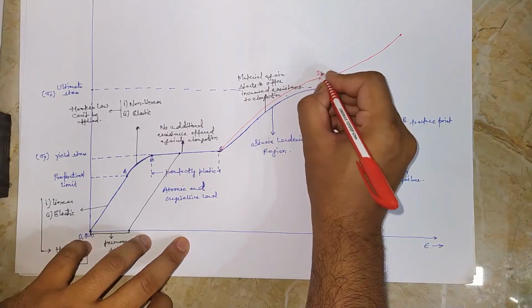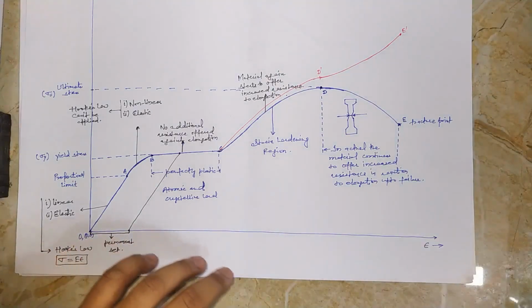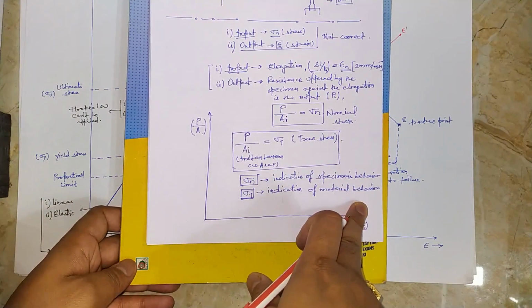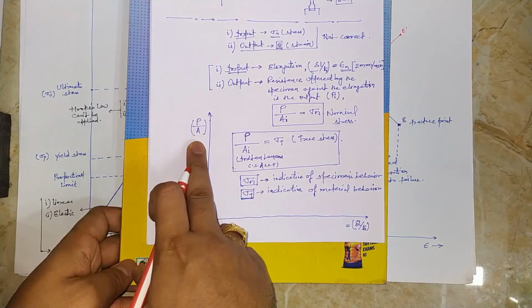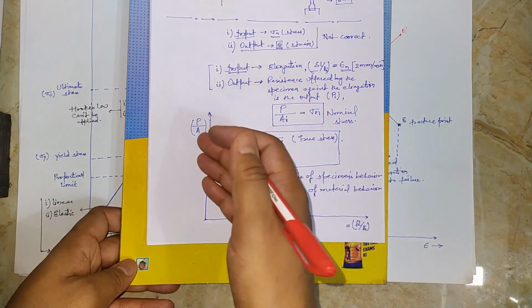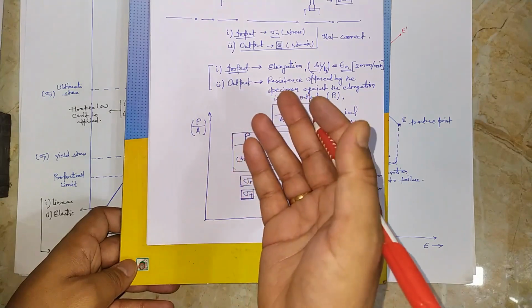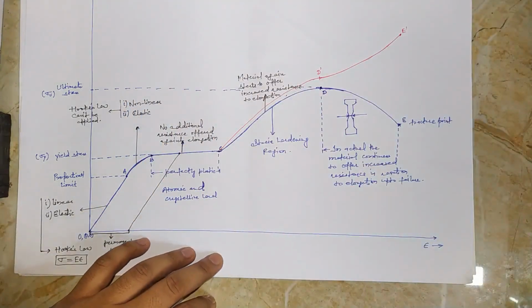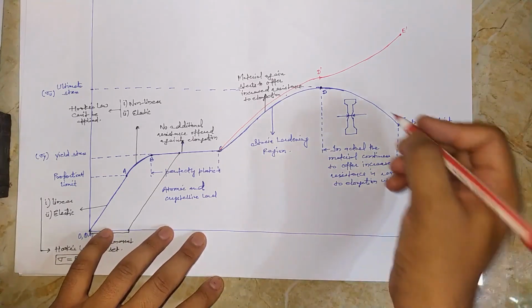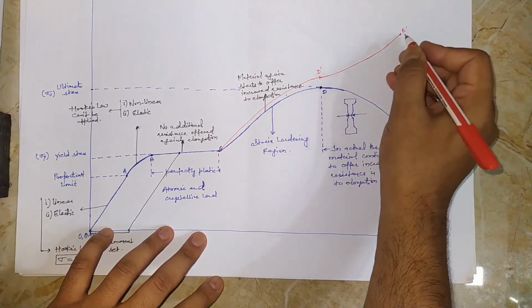Let us name these points D dash and E dash. I told you that true stress strain is an indicative of material behavior. Why? Because at every point we are eliminating the concept of the specimen. We are taking the complete material behavior. So as it was earlier indicated, that the material continues to offer increased resistance in elongation up to failure is quite evident from the graph of the true stress strain diagram between the stretch D dash and E dash.